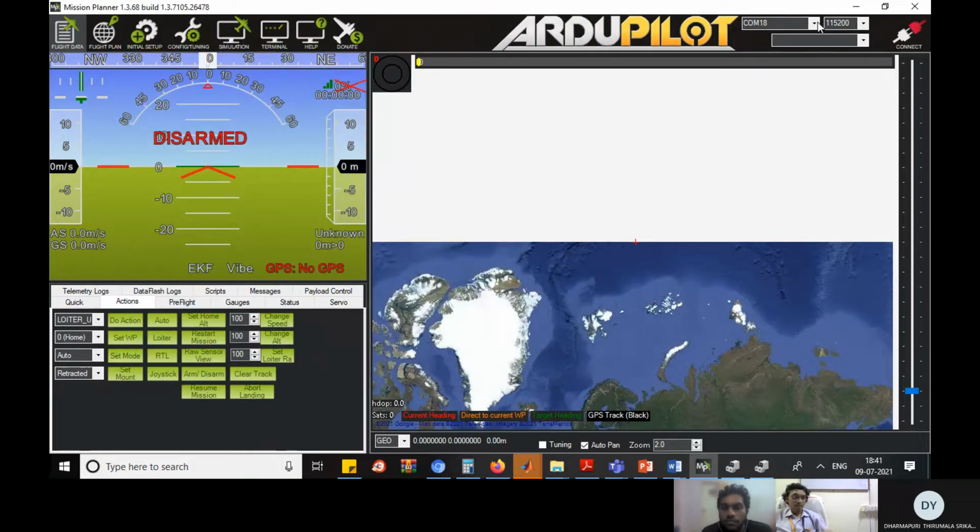So for the autopilot system, you have only two options. If you are connecting through the USB, this is a fast data rate transmission. Okay, you should go with the 115,200 baud rate when you are connecting USB, a physical connection. This is not available when your aircraft is flying. Okay, all are wireless at that time, so at that time you use the telemetry like this.